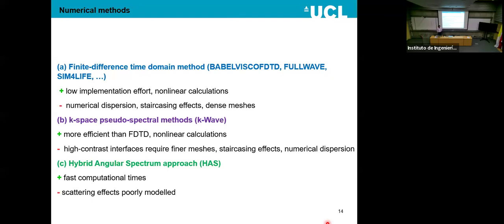Furthermore, the problem we're dealing with is generally a frequency domain problem, where we're switching the ultrasound on for a few seconds to induce a localized biophysical effect, but a few seconds at 1 megahertz is practically a continuous wave. So when you're using a time domain solver, you need to let the solution ring long enough to capture all the multiple reflections and to get rid of the initial transients, and that can be time consuming.